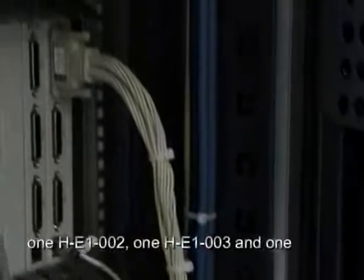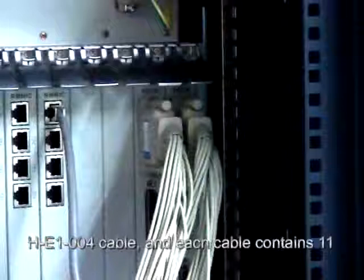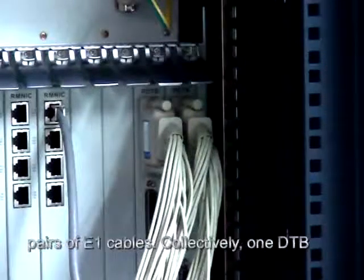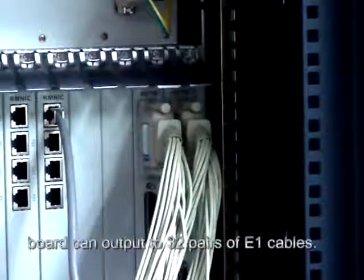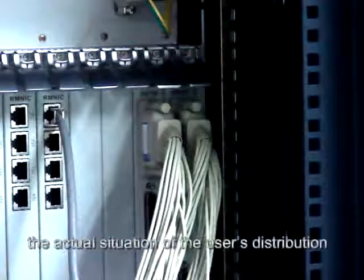Each DTB board can output one H-E1-002, one H-E1-003 and one H-E1-004 cable, and each cable contains 11 pairs of E1 cables. Collectively, one DTB board can output up to 32 pairs of E1 cables. Designate the terminal at NB in light of the actual situation of the user's distribution frame.